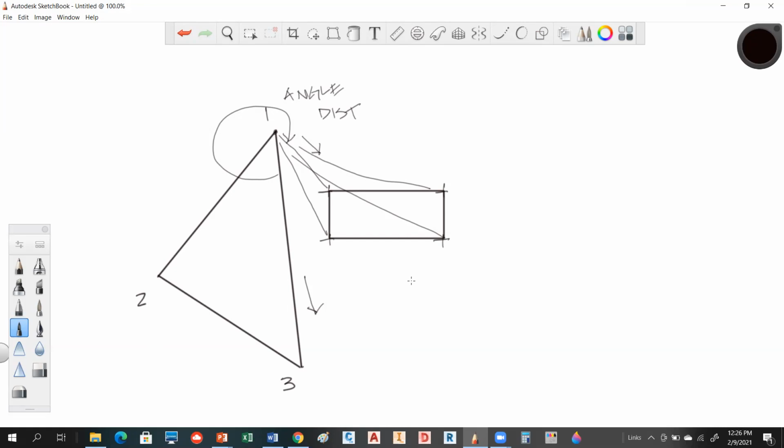So if you were using a GPS system, instead of having a control network like this on the ground, your control network is your satellites up in the sky. You still have this given, and that's given, and that's given, and that's given. And then the satellites position you into that spot. But you're going to have centimeter accuracy, so you're going to get a little bit better accuracy on these kind of things. So it does make a difference what you're doing.